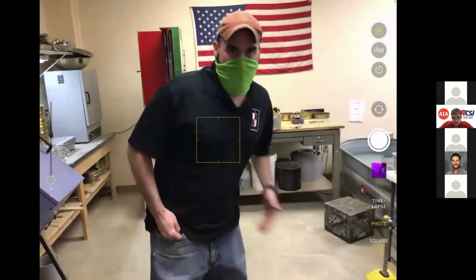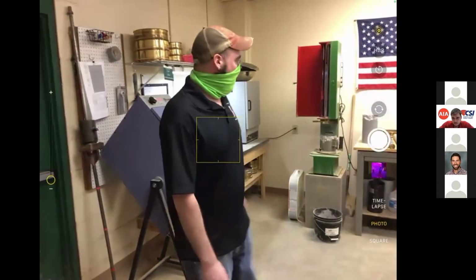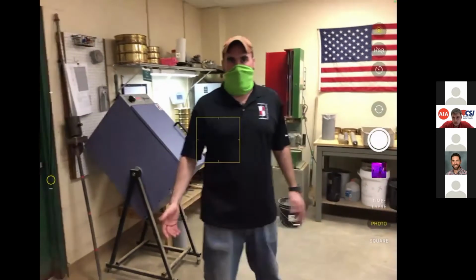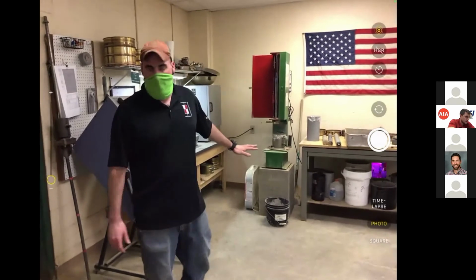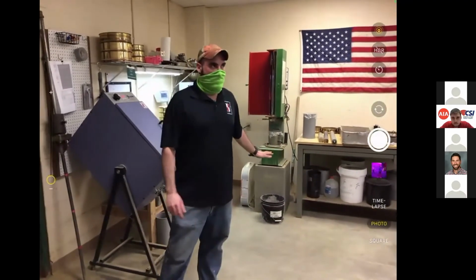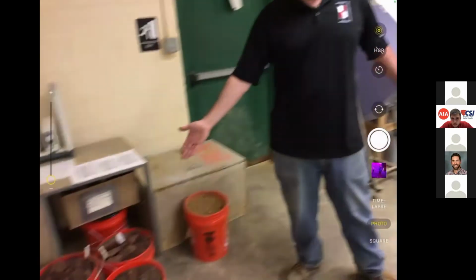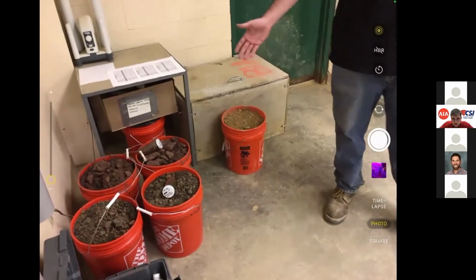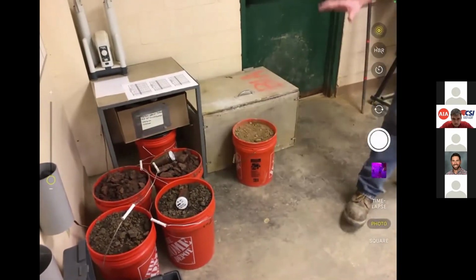Like AJ said, usually the first thing we do with projects is soils work, and some of the first things that includes are proctors and soil classes. So we have a lot of that set up over here for you, and we're going to run through a bit of that today. One of the first things we usually do, we get buckets of soil from the job site and bring it in. The first thing we do is dry it out. Usually we spread it on the floor and get a fan on it. Once that's done, we bring it over here.